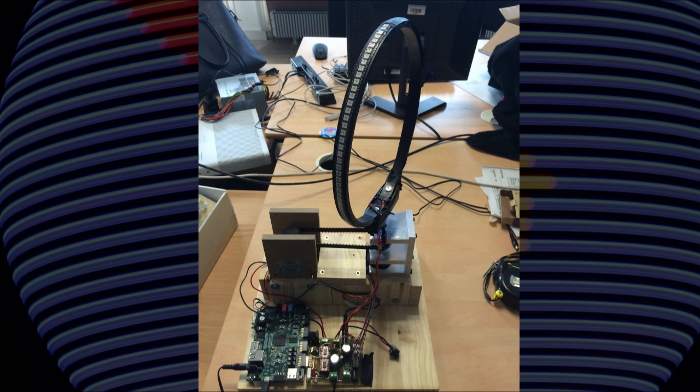So, how does the globe work? We use a LED strip put on a rotating ring to give an impression of a full globe of pixels. Then, we change the pixels in synchronization with the globe rotation to display the columns. We can display images at a resolution of 100 by 49 pixels. The strip needs 32 bits per pixel sent with the serial protocol. The first 8 bits are global values, which leaves 24 bits for coding the colors.